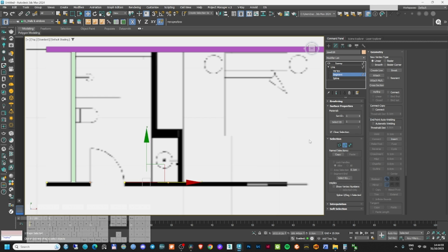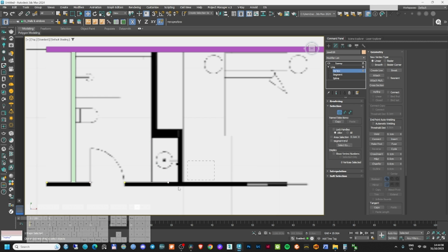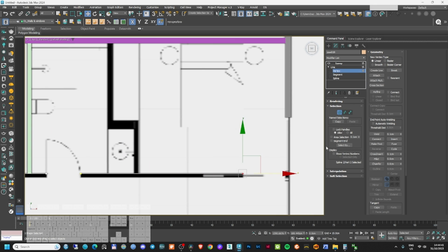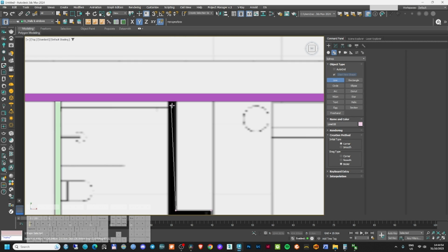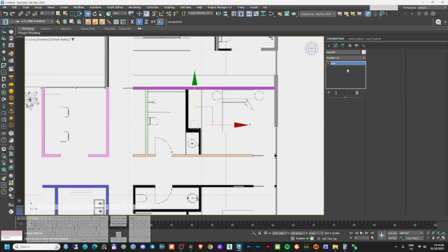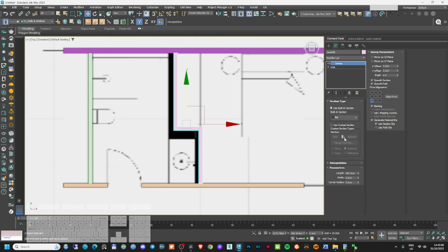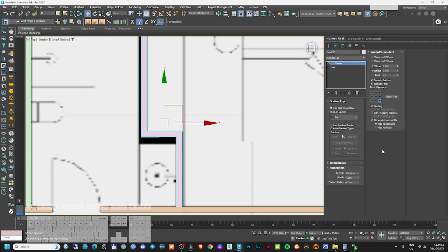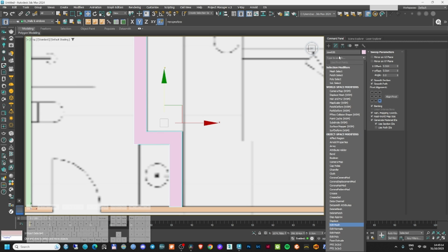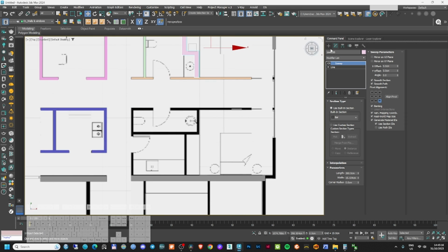By using Ctrl Shift, you can make a copy of a wall that you already have. Probably I'm not going to see all of these walls, but I'm just going to create them just to be sure that my 3D is gonna look fine. Here I can add them. I'll just leave it as it is, it doesn't matter.